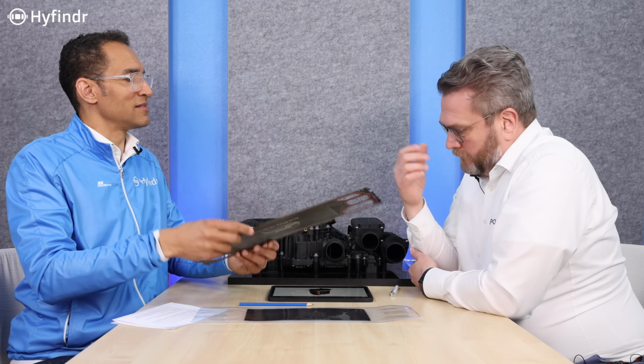So for example, if you have a heavy duty truck traveling uphill, you need more power. And you need to have more ability to reject the heat. So that's why you allow 105 degrees C at the outlet for a short time. Ah, right. So the truck traveling uphill means that this thing is also changing in situations. Sure.